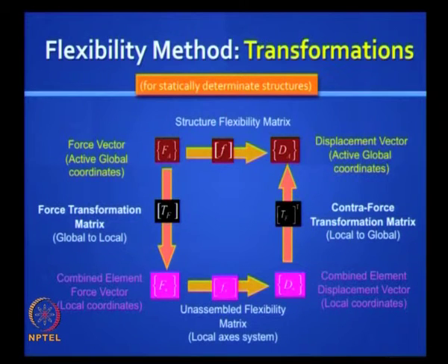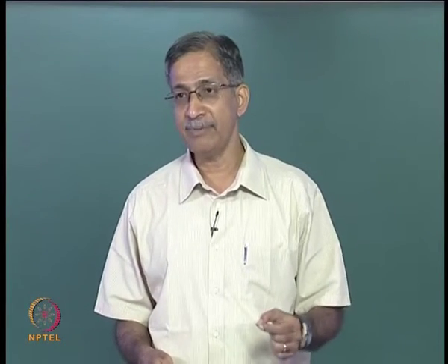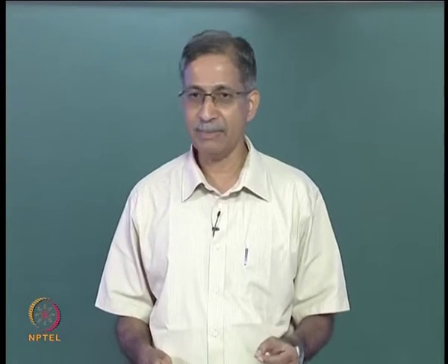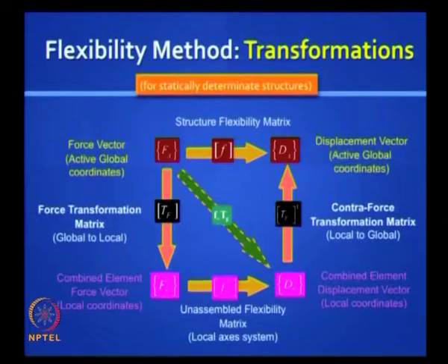We have done this in module 3, but we will refresh in this module as well. And this is the reason why in statically determinate structures you do not have to explicitly satisfy compatibility. It is automatically satisfied when you apply static equilibrium equations, and of course you have this diagonal which allows you to shift to the element deformations from the load vector directly.